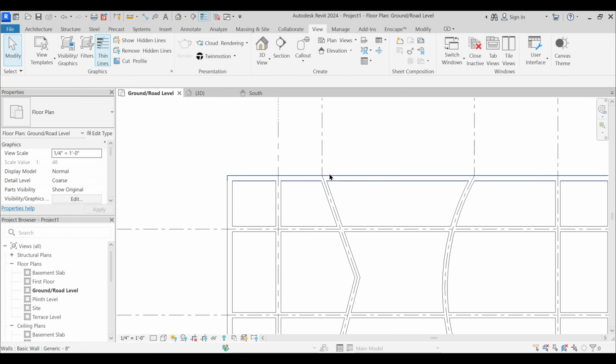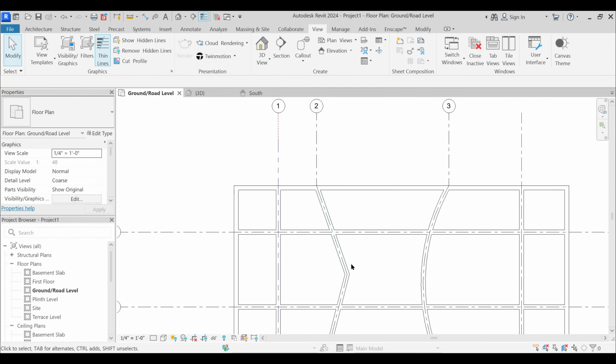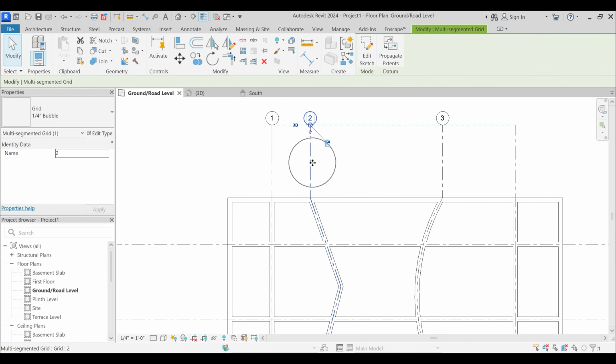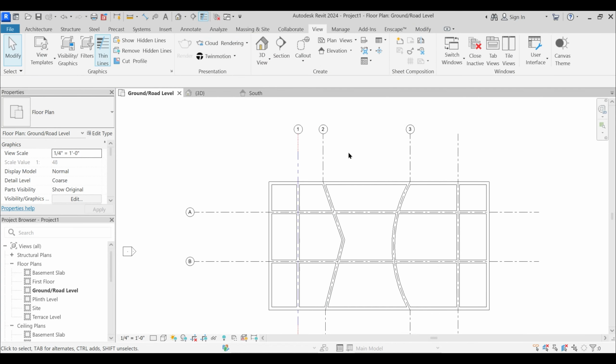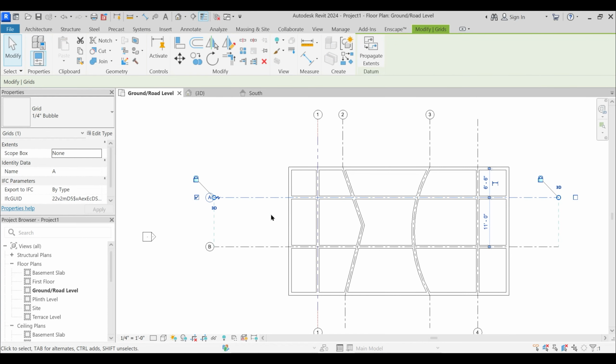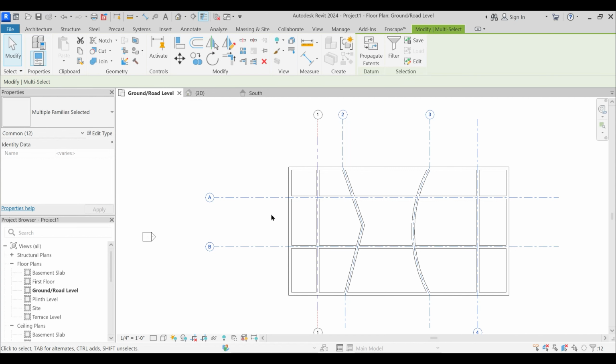And you see, as I said, whenever you use this multi-segment, the pattern which is provided by default works properly. If you place any customization, it won't properly reflect. I don't know why it's like that. But if I select any of these particular grid lines and press SA, that is Select Similar.